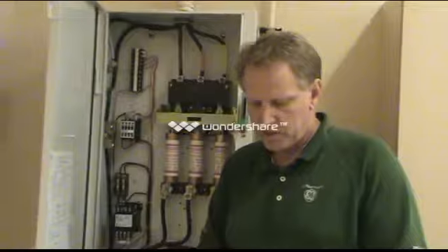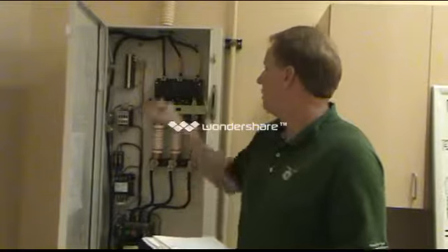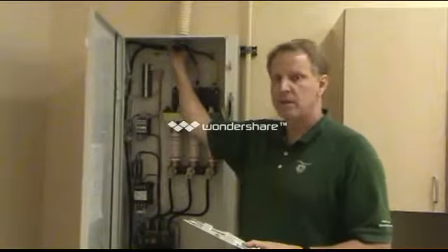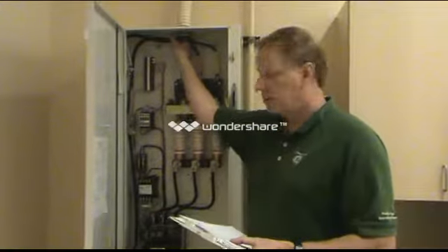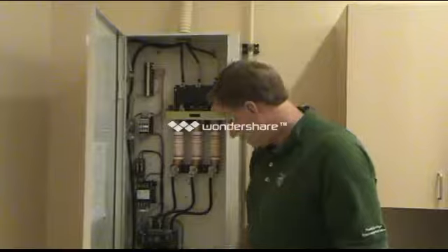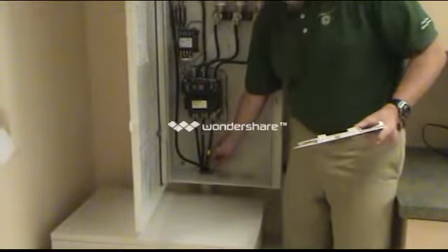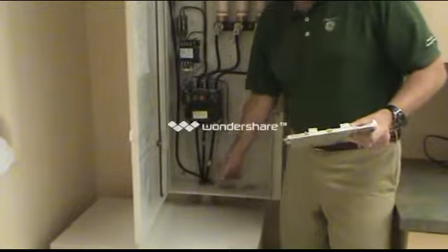All right, question 11. Do the cable ducts have dividers separating power and signal cables? Inside your power conduit, you should only have your 4 or 5 wires, your 3 phases, your ground, and possibly your neutral, and that should be it. No other signal cables coming through. In this case right here, down at the bottom, we do have some signal cables. So this would be something we would write up.